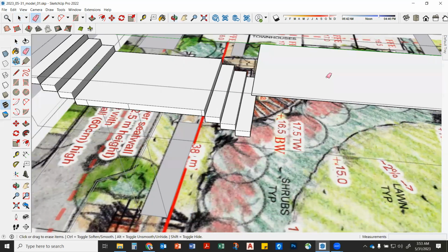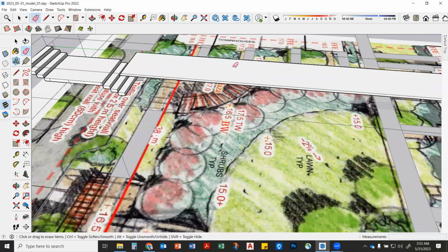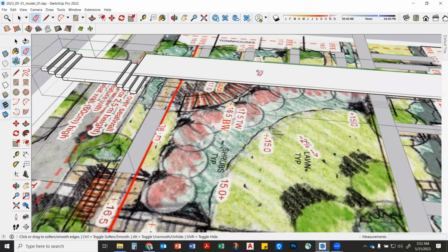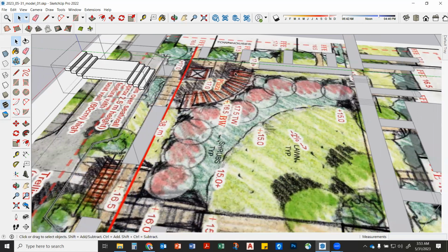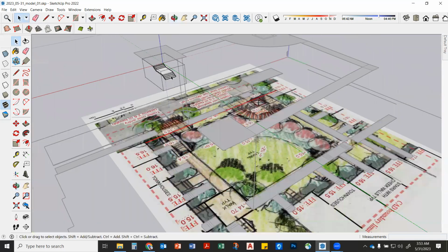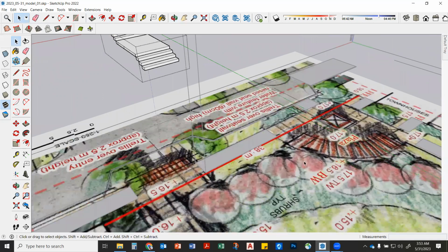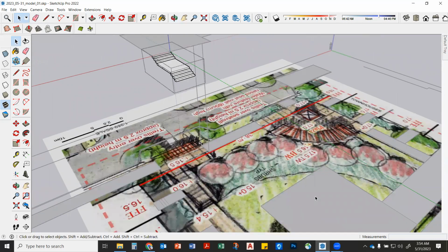Cleaning those up. Then I could actually just come over here. I don't even need this guy because he's not correct. Oops. The easiest way to delete all those faces is to triple click, got all of them, delete. Okay. Now I've got my stairs, and I want to connect that down here. Now I know this is 2 meters wide, so I could come down here and start. I can make it inside this group, right? Or I can make it inside this group. It doesn't matter.